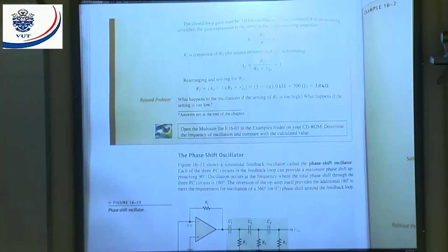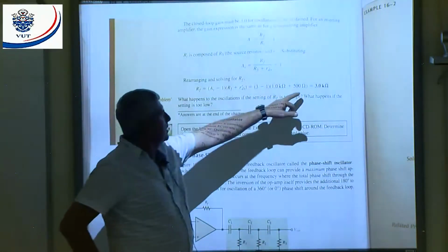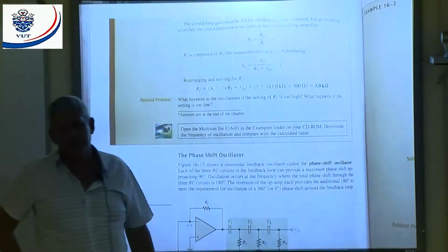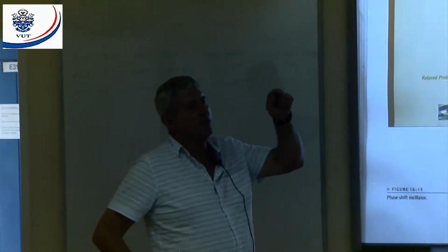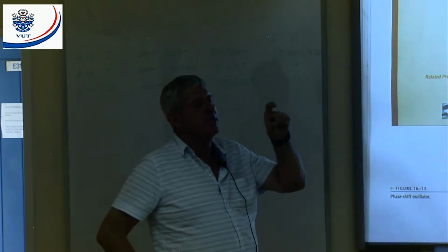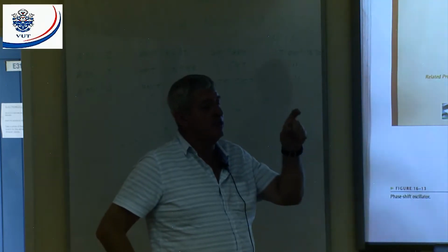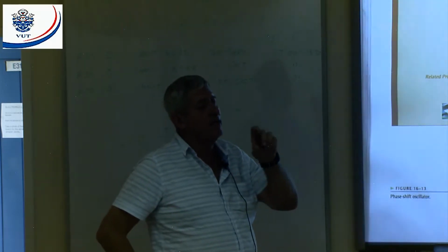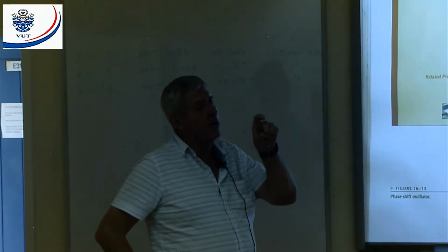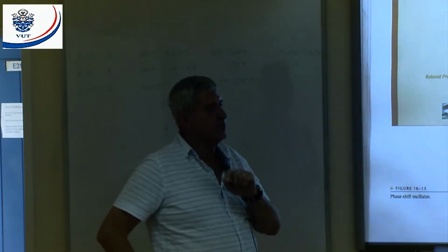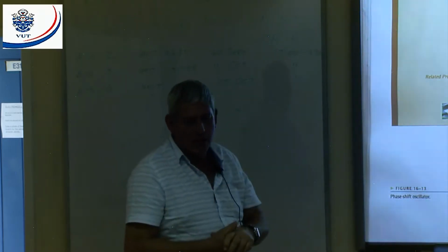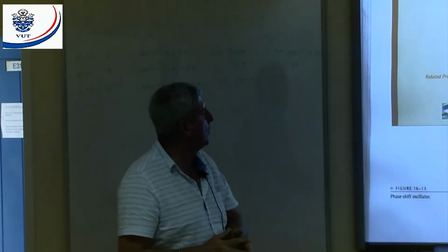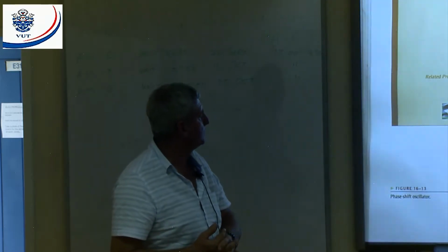You must remember those two resistors are going to be in series, all right? Because the JFET, between the drain and the source, there's going to be a certain resistance. But how does the JFET operate? If I vary the gate voltage, what happens? That resistance is going to change. Why? Because the depletion area can become smaller or larger, all right? Depending on the voltage on the gate.